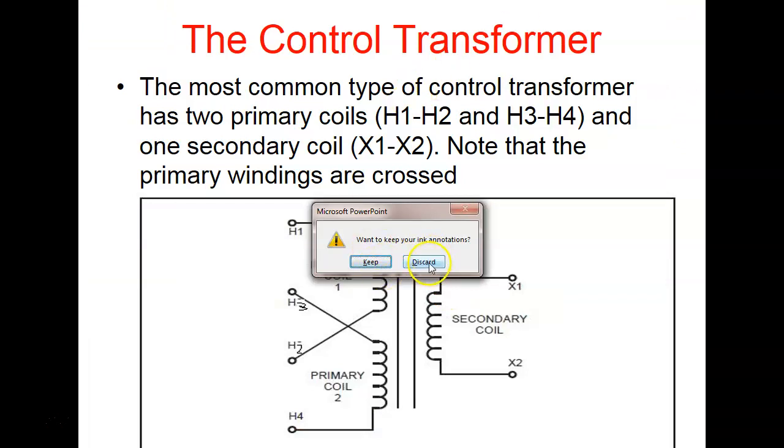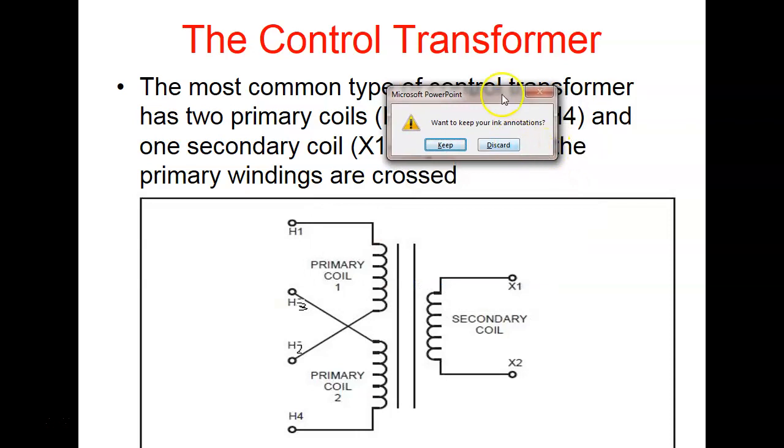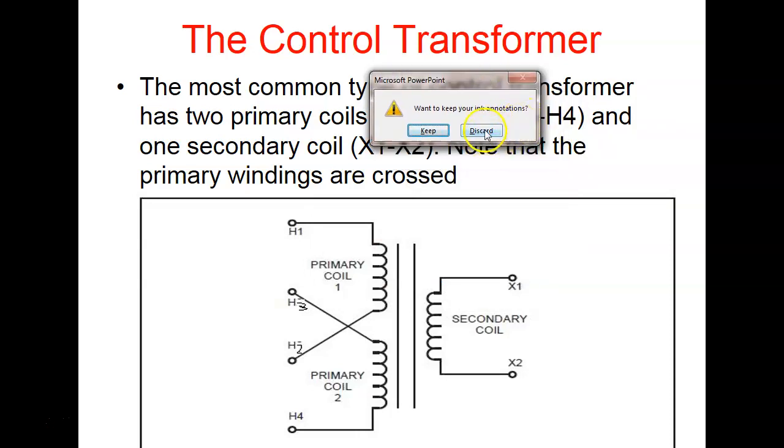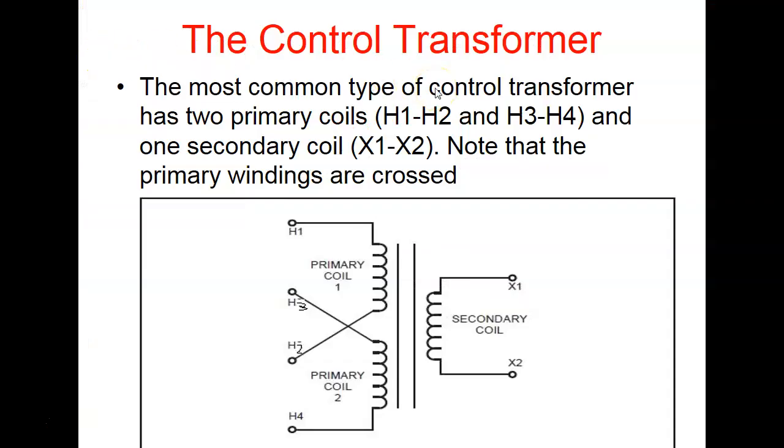Yeah, so the lower the voltage, the more current's required. That means if I want this thing to divide by 2, then I'm going to require fewer turns in my primary, but the current's going to go up in my primary. So if we're going to wire this thing to divide by 2, we want to hook the coils up in parallel.